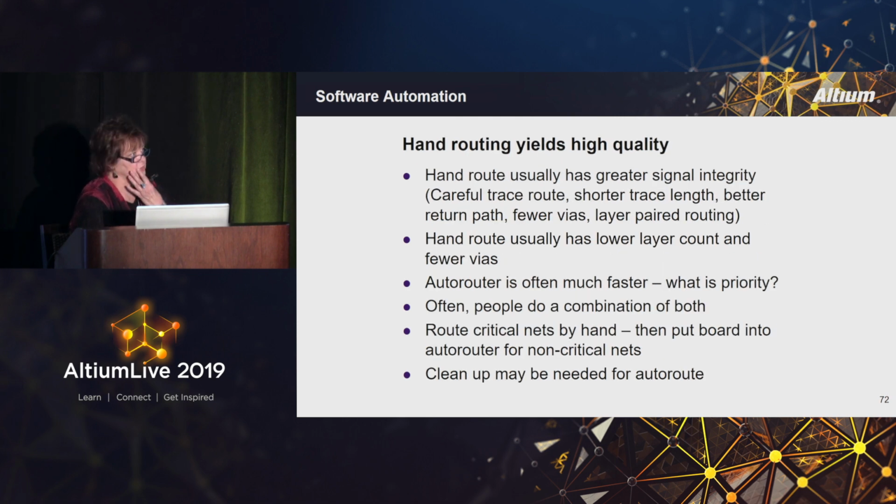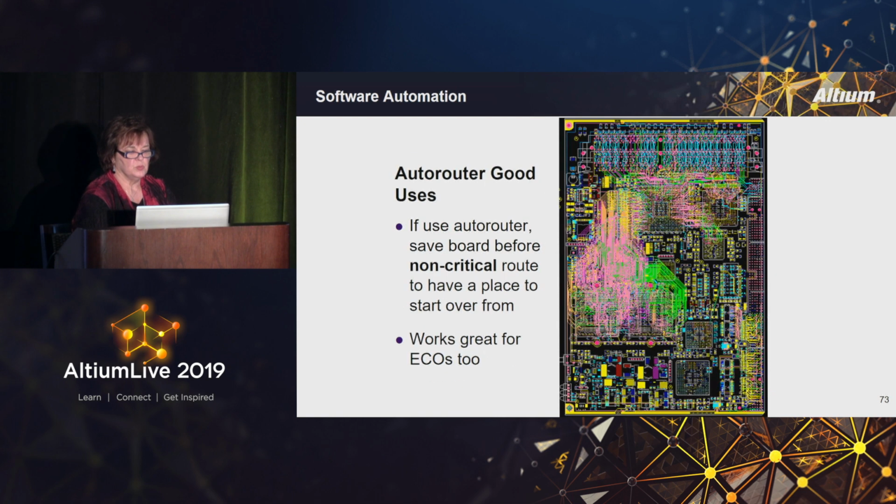However, I know that hand routing has very good signal integrity, and it will give you a careful trace route, shorter trace length, better return path, fewer vias, all those kinds of things. And Ben's chomping at the bit to get up here, so I'm going to quit talking about that slide. I just wanted to show this one picture.